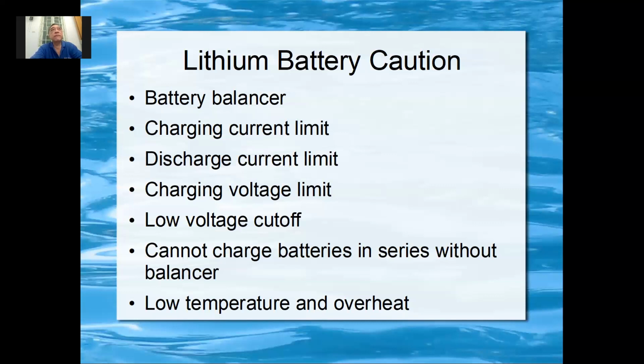And if you have 2 12 volt lithium batteries, you don't connect them in series. When you want to charge, you can charge them separately. That means you disconnect them, treat them like 12 volt, put them in parallel and charge, then both will get fully charged. Put them in series and treat them like a 24 volt battery and charge, then one will get fully charged, the other one will be undercharged, because no 2 batteries are the same.